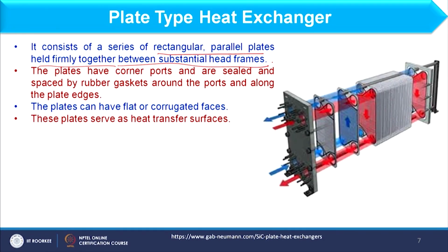Fine. Now, if you see this schematic, this structure, okay, this rectangular plate and this bar, and if you see at the top we have this bar also, where these plates are hanging. Okay. So, this bar is available at top as well as bottom, both sides. Okay. So, each plate type heat exchanger has plates which are arranged parallel to each other like this and this, and they are held firmly together with a substantial head frame. Okay.